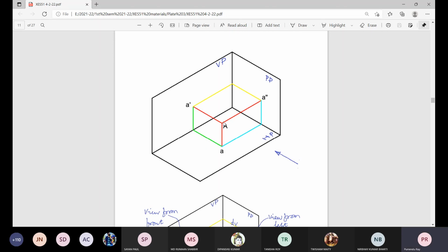We considered one particle, capital A, in this first quadrant. You project it, that means you draw lines passing through this point, capital A, perpendicular to this vertical plane, and this is the foot of the perpendicular, as if here is one light source and that torch is giving us this shadow. Now the name of this point has its specific rigid grammatical guideline, that is lowercase a with a prime. Sometimes we call it small a dash.